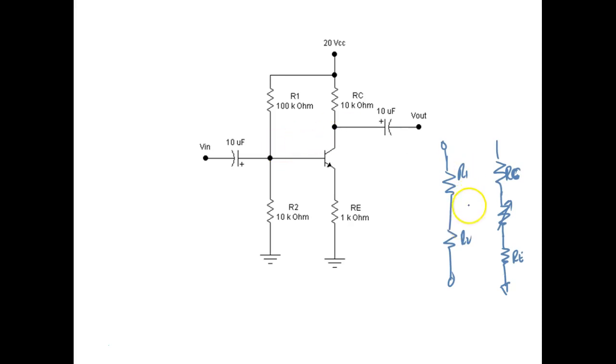So if I calculate this resistor there, what would be the voltage across R2? R2 sets the base. That's going to be the base voltage. Because notice my input signal is going to be right here. And so my input signal is connected to the base, but it's common to the emitter. So we call this a common emitter amplifier. Common emitter amplifier has nothing to do with your power supply common. It's what your signal, what you're trying to amplify, is common to.